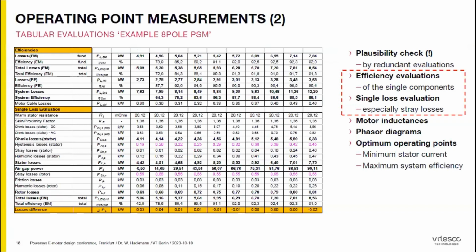For our special analysis, we then have a single loss evaluation, where all these single losses are summed up. And this would be a topic for the validation of the finite element simulation. We want to check the ohmic losses DC, but also ohmic losses AC, meaning the frequency dependent part of the ohmic losses. We want to have a view on the hysteresis losses in the stator, the stray losses, harmonic losses in the stator, harmonic losses in the rotor, friction losses, and also stray losses in the rotor.